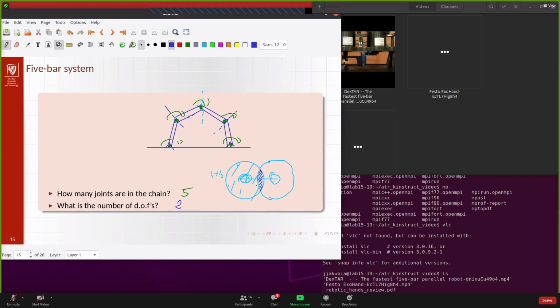Of course, depending on how big the base is, they can be bigger. They can even start to cross in that part, and then the shape will be more complicated. But that's more or less how you get it. You combine these two shapes of the separate double pendulums' workspaces, and you find the common part of it, and that's the workspace of this structure.